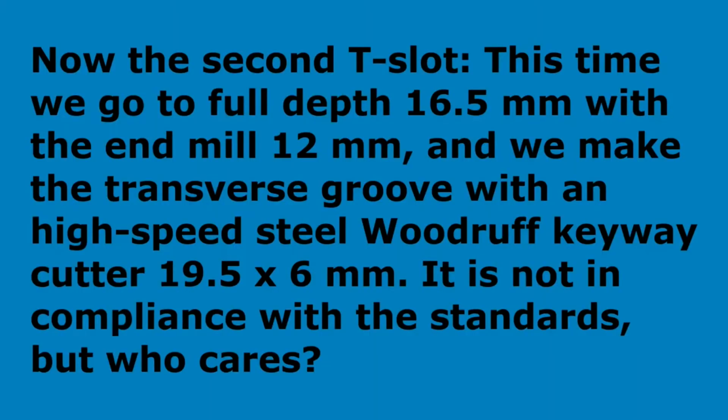Now the second T-slot, this time we go to full depth 16.5 mm with the end mill 12 mm, and we make the transverse groove with a high-speed steel Woodruff keyway cutter 19.5 by 6 mm. It is not in compliance with the standards, but who cares? It works and that counts.